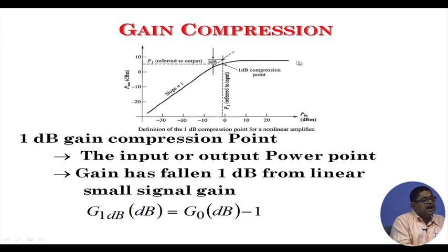Obviously, when it is flat, I know that it is a nonlinear thing, it is saturated. But here, people have decided that we will not say it is nonlinear yet; we will say that here it has become clearly nonlinear. This point is called the 1 dB compression point.